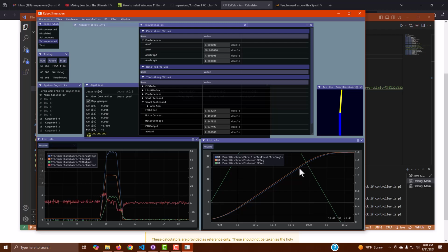We were actually with feed forward of 6, a little bit ahead. If you remember, the blue line was a little bit above the orange when the feed forward was 6.01. Now with it too low, we're tracking below. The PID always has to catch up. So we're going to be a little bit slower at keeping it on track, but we still keep it on track really well.